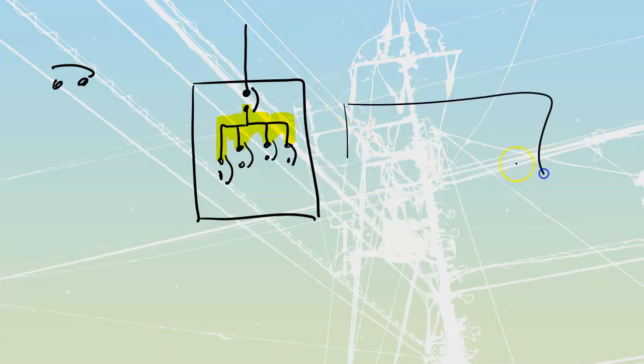What it is not designed to do is let us say, well, we've got a splitter, and maybe a 200 amp panel over here, and I'm going to come out of that 200 amp panel and directly connect the lines from my splitter onto these bus bars themselves. You're not allowed to do that, where you tap directly off of the buses.